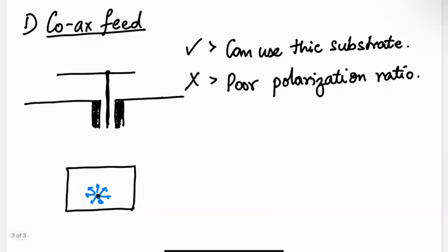because of that. Now, ideally, that should not happen because you're feeding it at this line of symmetry, which means that the current has to be divided this way. Whereas this mode has a current like this, so it cannot be excited by current which has both components. But there is still some amount of excitation of even this mode, and the crossport performance can be a little bit lower. There are ways to control that, but it's something to keep in mind.